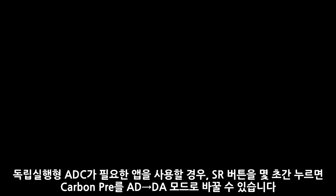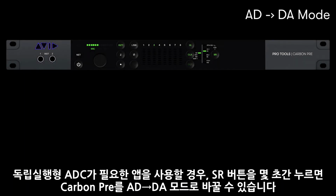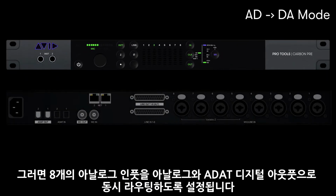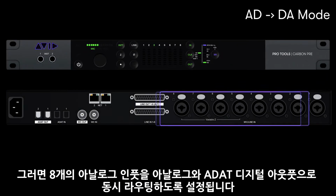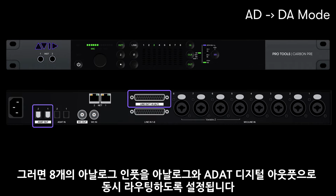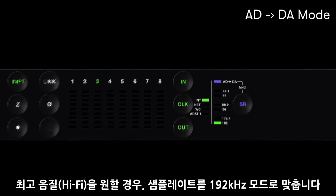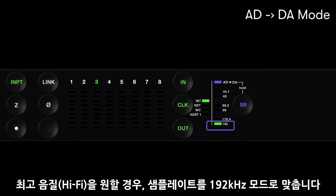For applications requiring the use of a standalone analog to digital converter, Carbon Pre can be toggled into ADDA mode by simply holding down the sample rate switch for a few seconds. This configures the device to simultaneously route the 8 analog inputs to the analog and ADAT digital outputs. For the highest level of fidelity, toggle the sample rate into the 192 kHz mode.